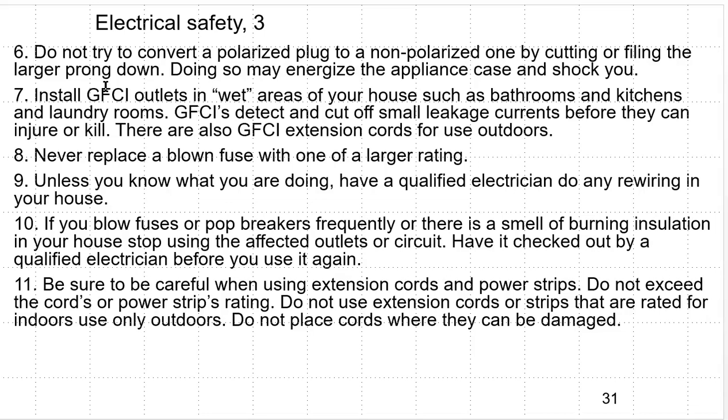Never replace a blown fuse with one of larger rating. Unless you know what you're doing, have a qualified electrician do any rewiring in your house. If you blow fuses or pop breakers frequently, or there's a smell of burning insulation in your house, stop using the affected outlets or circuit. Have it checked out by a qualified electrician before you use it again. It's not worth your life.